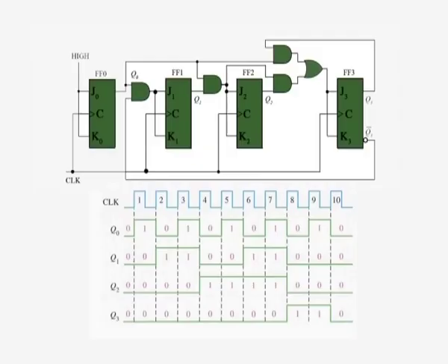A 4-bit synchronous decade counter. A BCD decade counter exhibits a truncated binary sequence and goes from 0000 through the 1001 state rather than going from the 1001 state to the 1010 state. It recycles to the 0000 state. A synchronous BCD decade counter is shown in figure. The timing diagram for the decade counter is also shown.